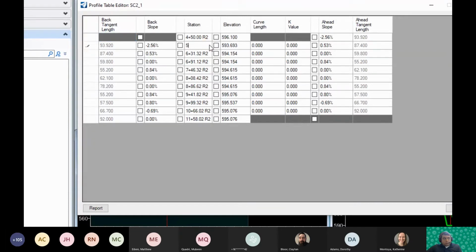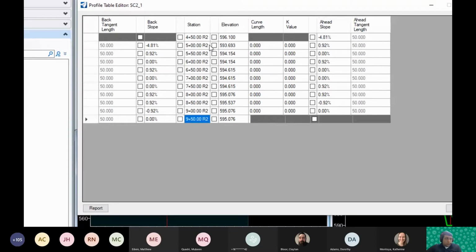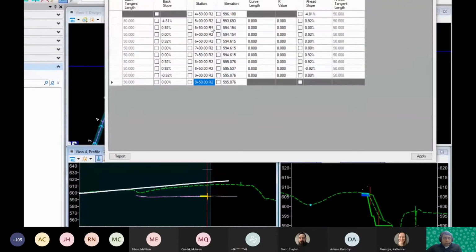So, I'm gonna do 5, 550, 6, and that moves all my vertexes to all those key stations that I'm gonna end up creating cross sections at those locations for, right? And then the next column is elevations. So if I did cut temporary drawing models for cross sections, I could use that and just quickly type in those elevations as I see fit.